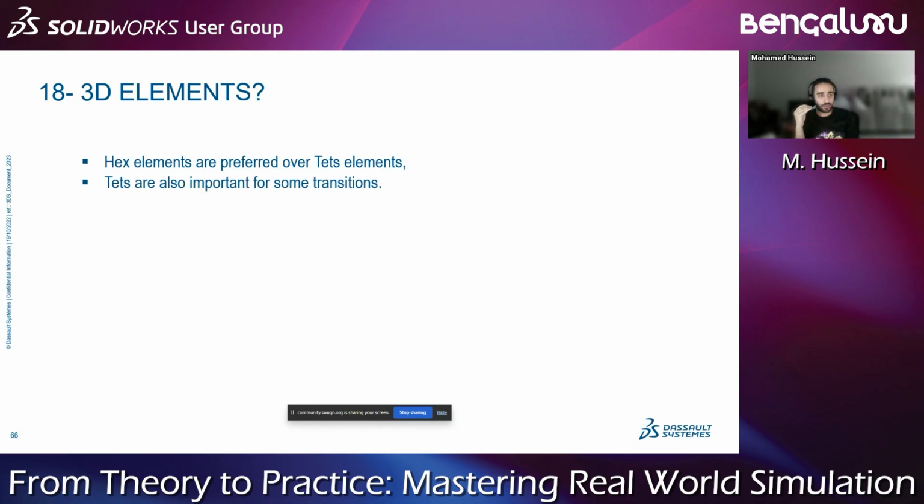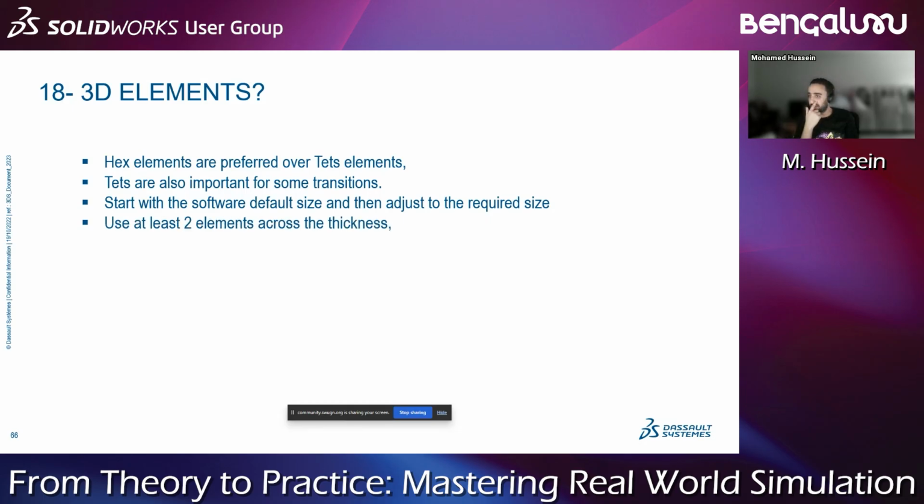However, if you are aware, in SolidWorks only tet elements are available. Tetrahedral elements are important for the transitions. Whenever you are doing your mesh, sometimes you start with your default size and then you adjust to the required size that you are using.